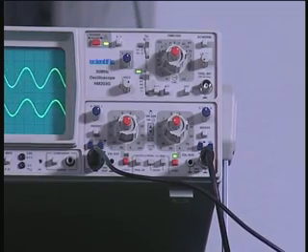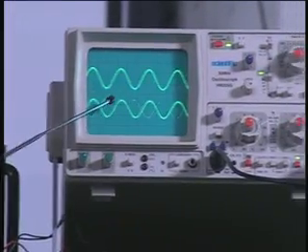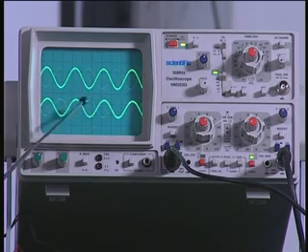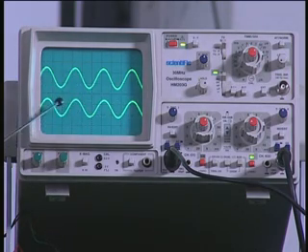The two traces that you see here are basically the input and the output both together. So, you can see they are actually in phase. When the input is going down, the output also is going down, they are in phase. But when I change the potentiometer, you would find one of the traces, the output trace, will show a shift that corresponds to the phase shifting that I am talking about. For the same RC network, if you change the value of R and C, you will get different phases. Therefore, you would find the shift in the phase as seen by the shift in the trace that you see on the oscilloscope.